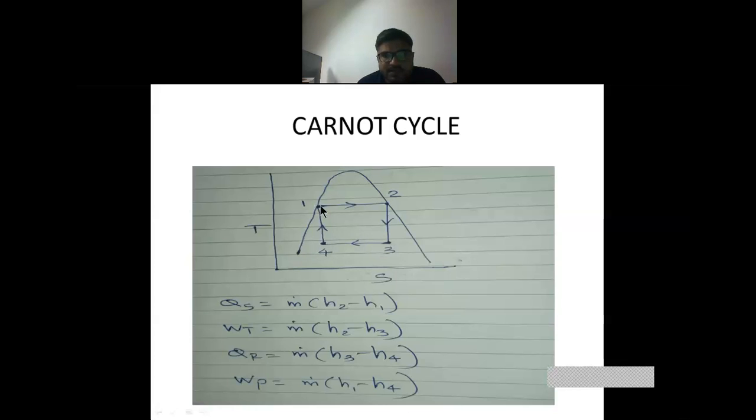And again here we can see heating at constant temperature. It is also very difficult in some regions. Generally, as you supply heat, the temperature always increases, so to heat at constant temperature is very difficult. Also, here you can see these are isentropic, but in an actual case it is not possible to expand or compress the working medium isentropically. So these are some of the limitations.